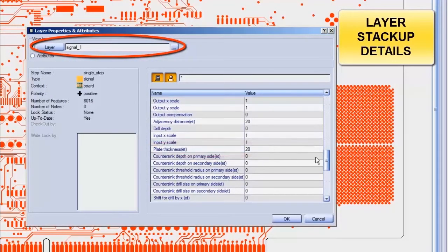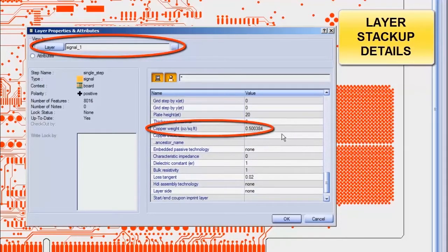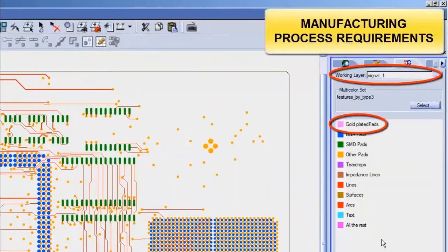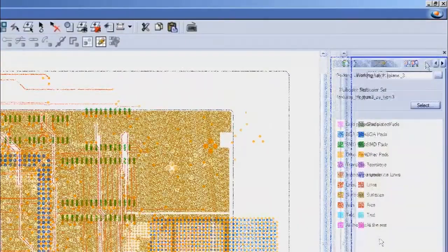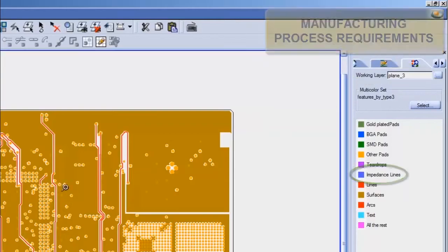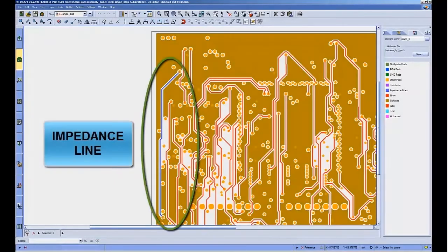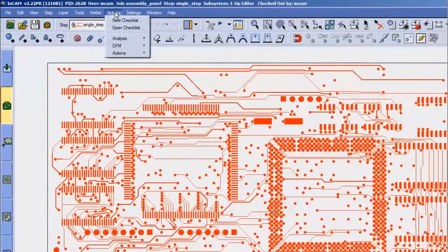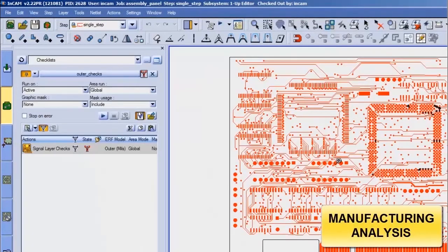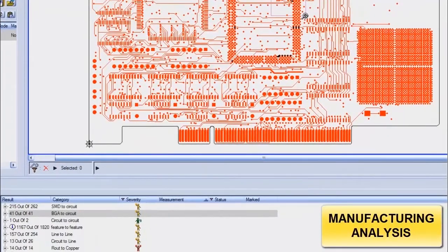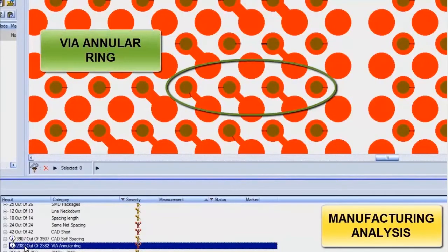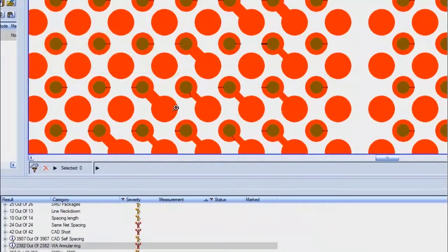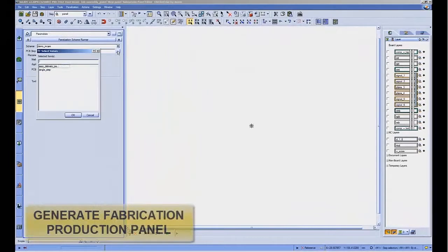Here we see overall thickness data and further multi-layer stack-up information. Surface finish definitions are defined and can be highlighted immediately for use in the tooling generation process, as can controlled impedance features. The process engineering specialist will always want to run his own DFM analysis, taking advantage of the intelligence in the ODB++ data, so as to validate manufacturability, but also to maintain the rules according to the actual manufacturing processes running in the factory.